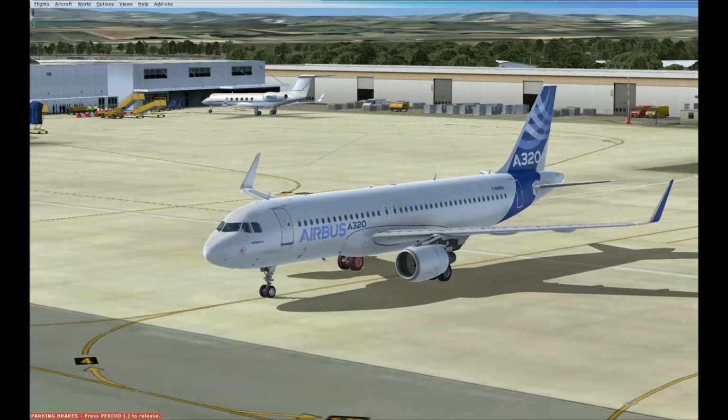In this video I'm going to look at flying the Airbus A320 using manual inputs into the autopilot. It won't use the FMC in any elaborate way, but we will need to use the FMC to put in our ILS radio frequency for our landing. Please note that this is not necessarily the technically correct way of flying the aircraft, but it will give a basic idea of how the aircraft operates on the autopilot and give us a general feel for the aircraft.